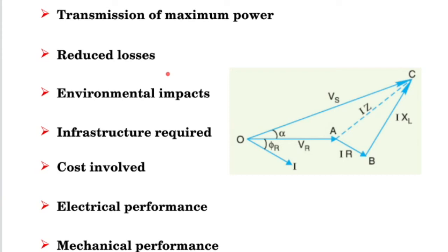Sometimes we might have some transmission lines nearer to agricultural farms as well. What happens is that from those agricultural farms, they spray pesticides to make sure that insects don't damage the crops. So they spray pesticides, and that can come and get deposited on the line conductor, and the insulator gets affected as well in that process.